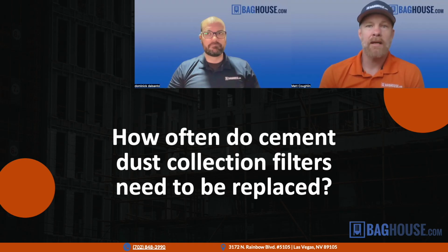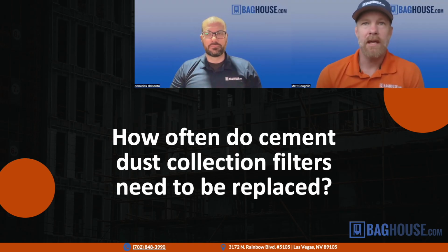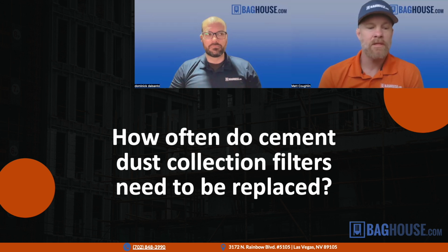That's a sign that the bags are nearing their end of life, and they're going to need to be changed as soon as possible. So what we recommend is people track the differential pressure. You should be checking it daily, weekly at least, so you have advance notice. If you're monitoring your process, you should have plenty of advance notice and be able to predict when those filters are going to reach their end of life.